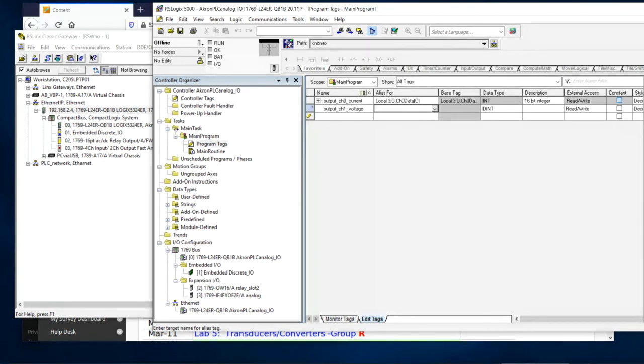All right, now the alias column. Remember that an alias means that this is a physical wired output. So what we're doing here is, if you have an alias, it means that you're actually physically wiring this thing out somewhere. So it's a physical real output as opposed to something stored in memory.